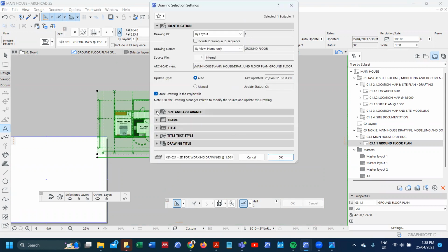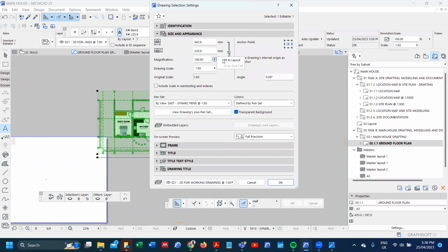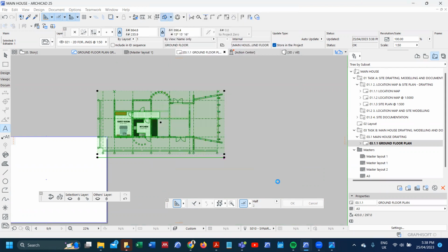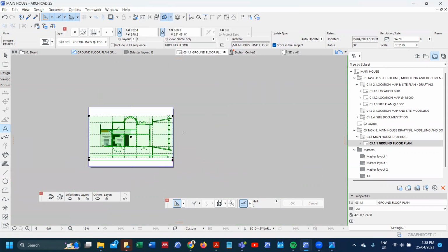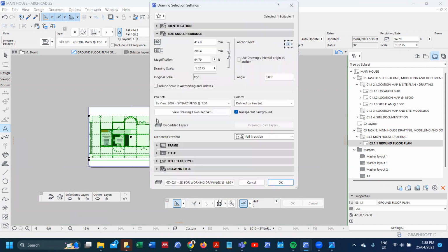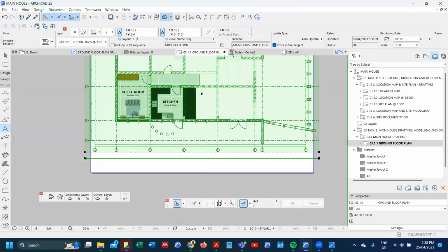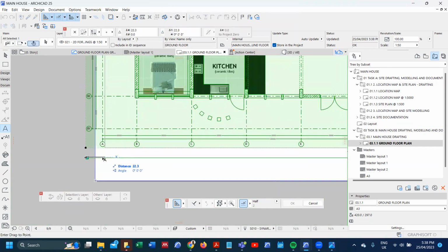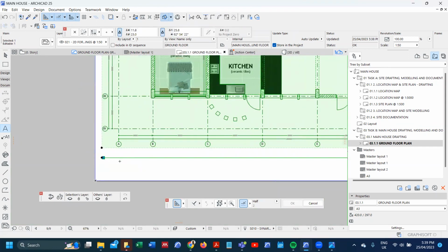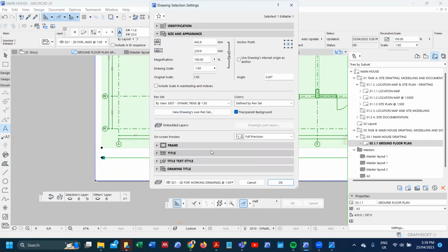I did not look at what size fits because I expected it to fit, okay? But in such situations, the scale of the drawing supersedes the size of the sheet, okay? The scale must be 1 to 50. So it means that in the event that the A3 does not fit, you need to look for the next best sheet, okay? In this case, it will be an A2. But for my case, an A3 is easily fitting.